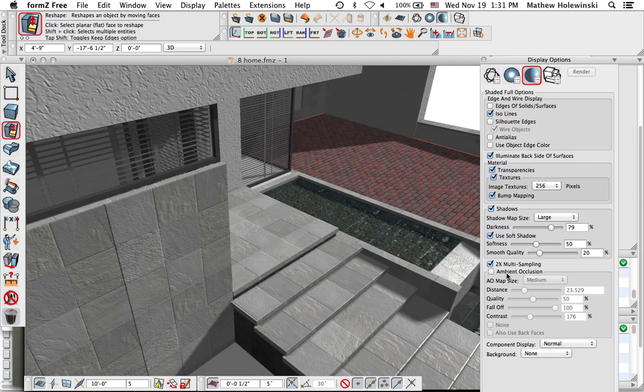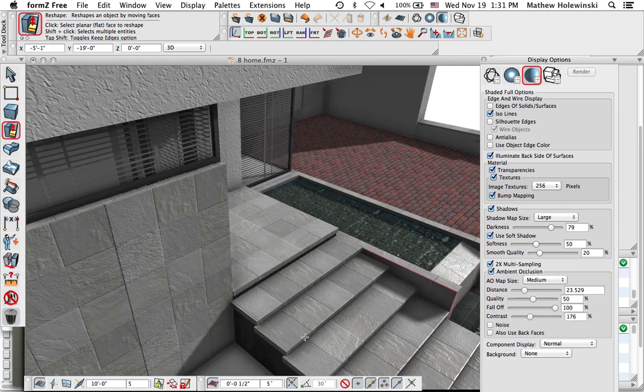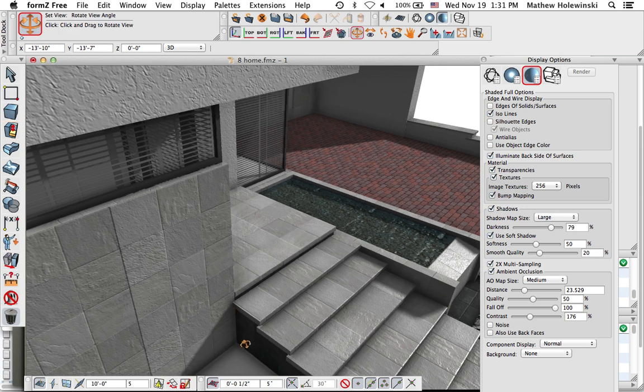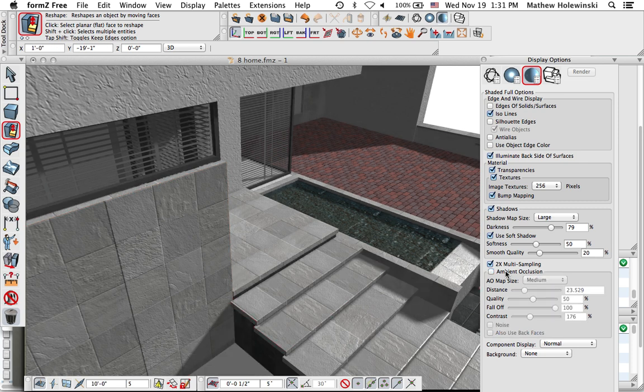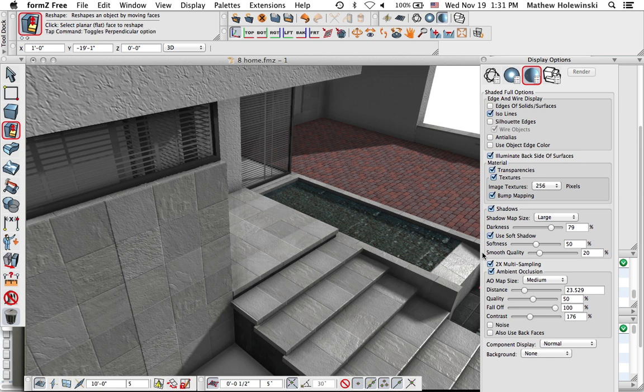This is real time. So normally you'd see ambient occlusion only in ray trace global illumination renderings. Here we're actually doing it live in real time. So as we're spinning our model and everything, you can see that we can turn that on or off. And that is just darkening where two surfaces meet. So it's sort of subtracting light in the corners and the edges and things like that, which just gives it a higher level of realistic effect in there. Okay. All right. We can also do live dynamic texture mapping.